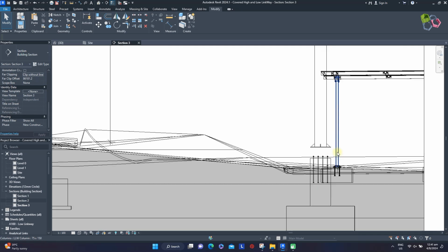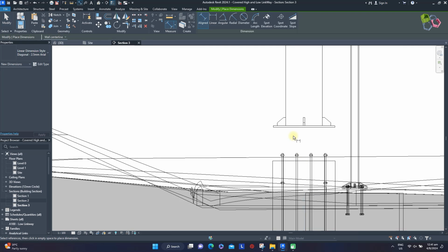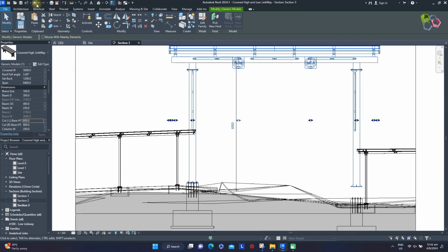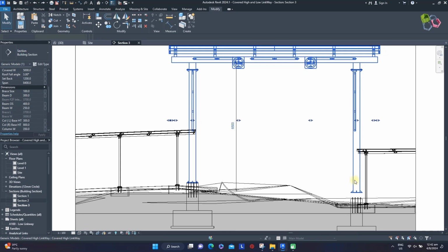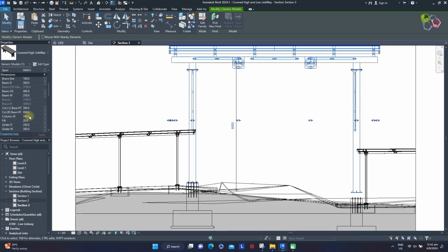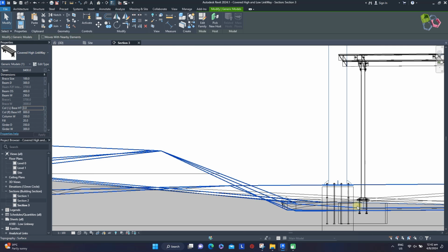Let's measure here for dimension for the next two columns. 320 mm to be longer. Select the family in the Properties panel. Add column left base 3,000 plus 300 mm instead of 320 mm. Place equal sign in front. Apply. Alright, good adjustment for that particular column.